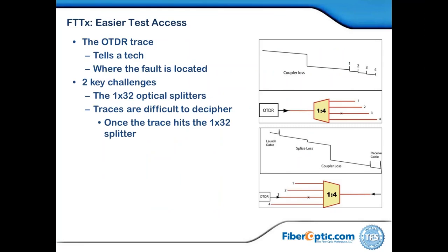Now, I did throw a couple of testing slides up here, and you heard me say earlier that it's very difficult to get a good OTDR trace. So therefore, I'd probably want to disconnect at the FTTH and shoot back to the central office. And here is what the OTDR might typically tell you as you hit a coupler and you have a dramatic drop.